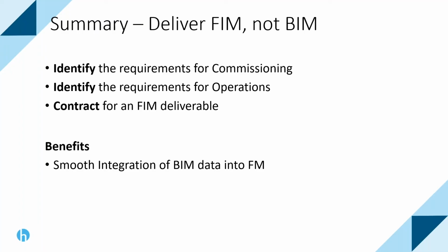The benefit to you, though, of working through this and thinking about how to create a clean model is that you're going to have a smooth integration of BIM data into FM. Because just about every client I've ever worked with who had a Revit model in Archibus, there was no problem connecting the Revit model to Archibus. The problem was that the data wasn't there. The data wasn't cleaned and ready to go. So it took weeks and weeks of cleaning and preparation to get to that point. But once you get a nice clean model, and if you can, order it in advance, actually linking Archibus to Revit is quite simple. And you'll see that next week when we talk about that.